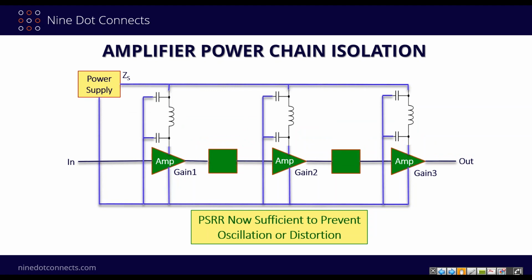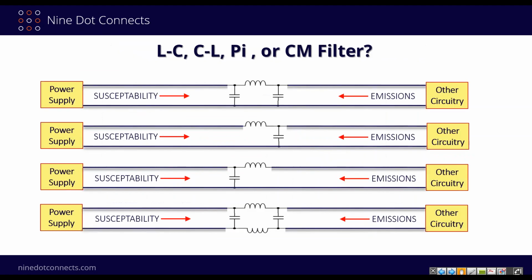This brings up another thought. If you're going to have a pi filter or some kind of filtering between your power supply and the other circuitry that it's powering, you'll have to throw some kind of an inductor in there, because this is a typical design problem. But if you go and have this tested for EMI, they're going to put some noise on the power supply side and ask, is this going to disrupt what happens in your circuitry? Or they're going to measure what's coming out of your circuitry and see if that actually makes it back out to the power supply.